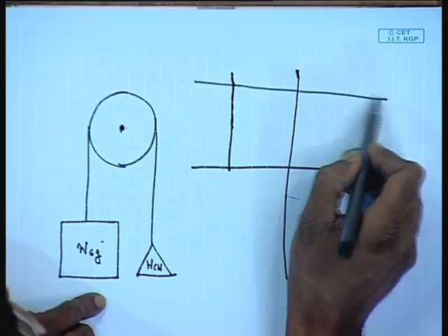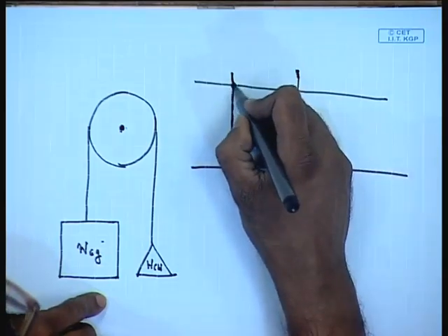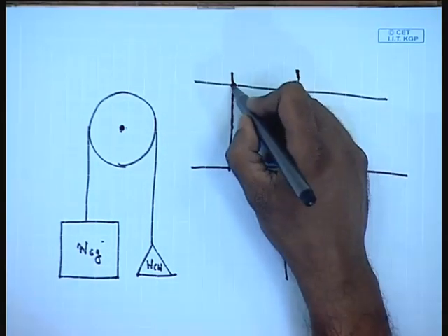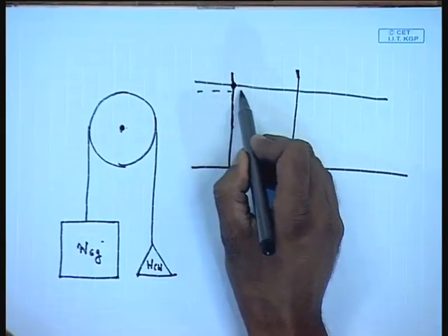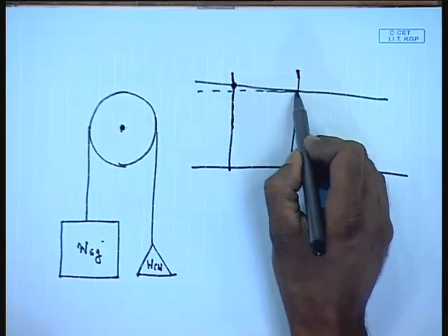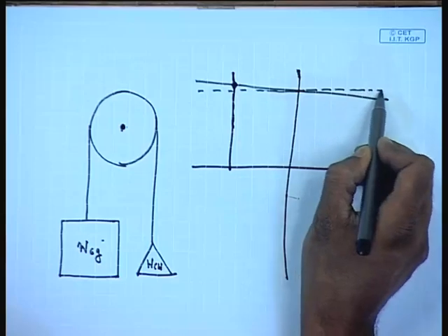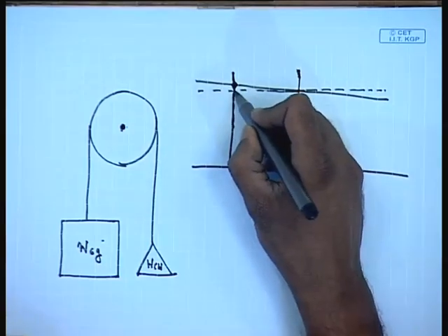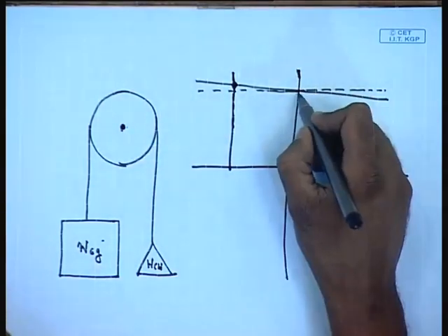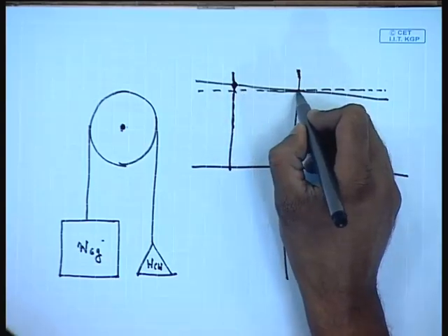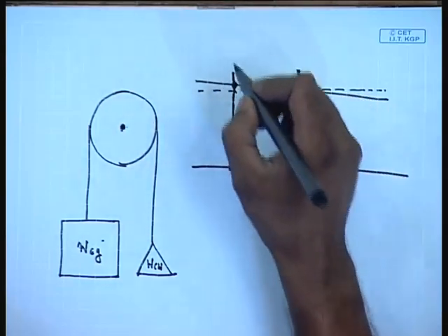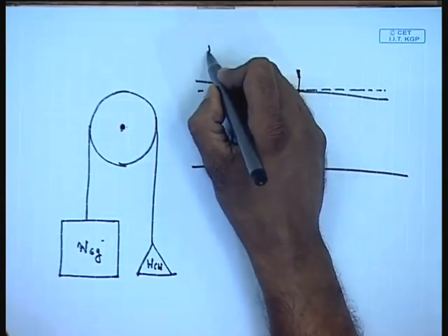Now we see that the operating point shifts to the second quadrant, that is the motor machine now acts as a generator and produces generating mode torque. The machine runs at a speed somewhat higher than its no load speed and feeds power back to the supply. This is called the regenerative braking mode of operation.